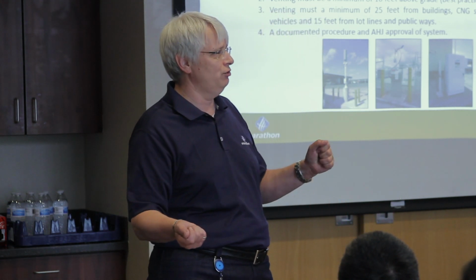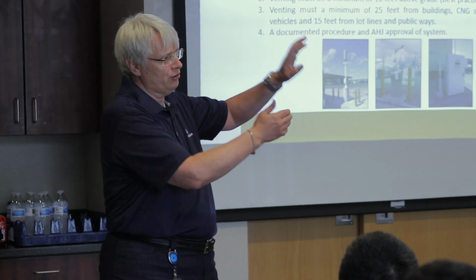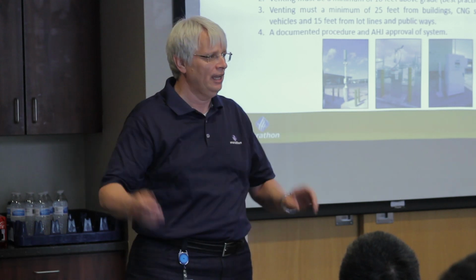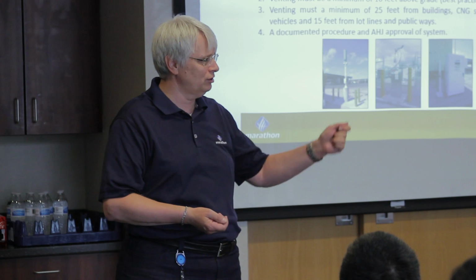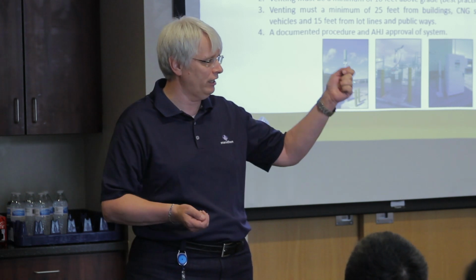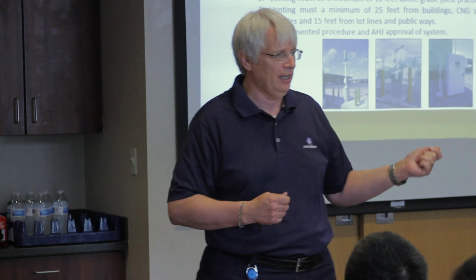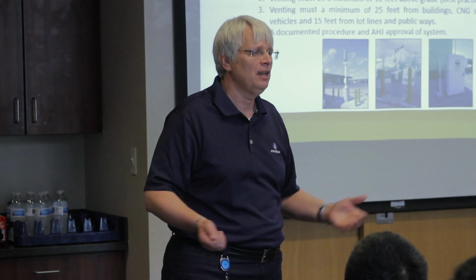So the first thing you do is you close off all the cylinders on the vehicle that you're trying to defuel, except the tank that you actually have to defuel. And then you find an empty vehicle. And the cylinder transfer hose, or vehicle transfer hose, just allows you to dump the gas from that one cylinder into that empty vehicle. And you do that for 1 or 2 vehicles. Try to get the pressure down as far as you can.